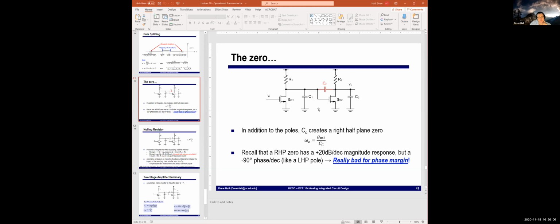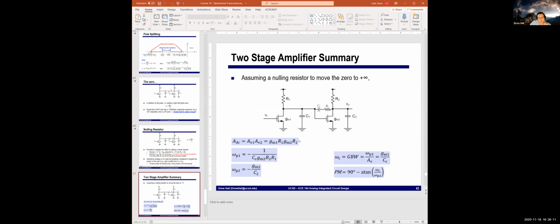And then essentially this, right? Yes, this, because what we're doing on the project is a two-stage amplifier. The second stage actually looks a lot like exactly what's drawn here. The first stage is a little bit more complicated than this in the sense that R1 is not just a resistor. This GM1 is actually very easy to calculate. It is the same GM as a folded cascode. It's the output impedance that's a little bit more complicated, and there are going to be additional poles that can affect both your phase margin and whatnot.